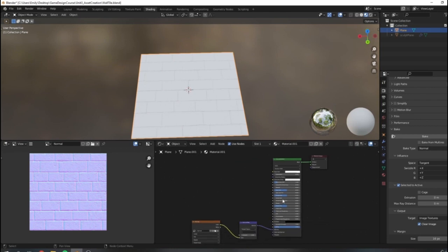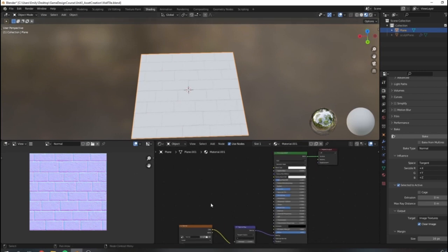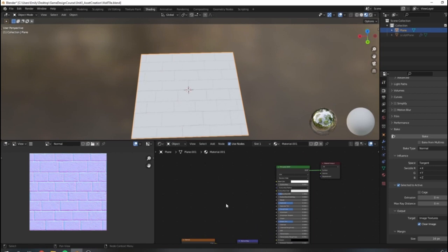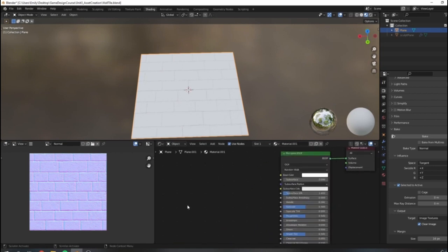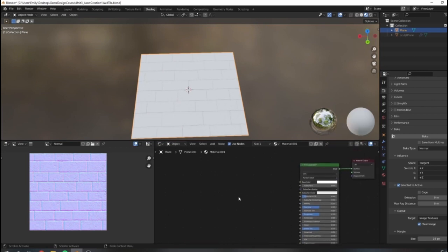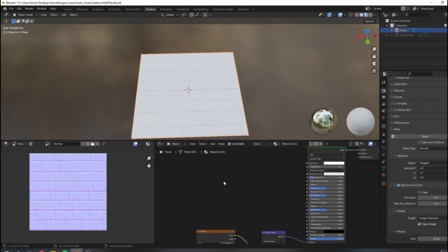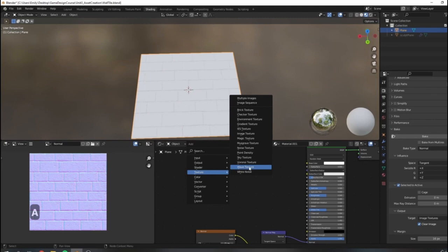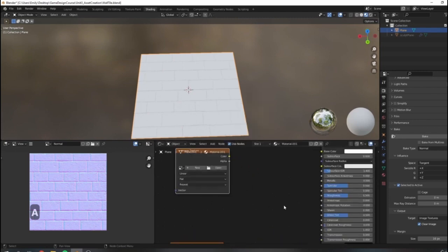Again, because the ambient occlusion is a black and white map, much like an alpha. Wherever the white areas are, they're going to be fully lit, and wherever the black areas are, they're going to be rendered as being in shadow. So it's important that you have a good basis to start off with a value of pure white.